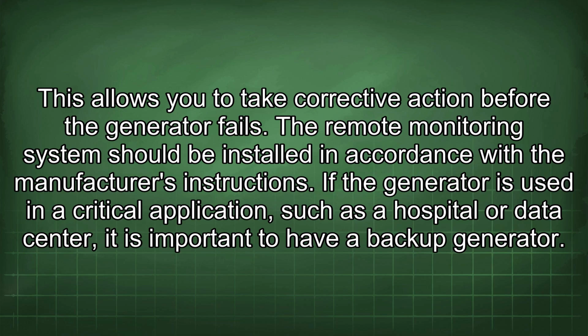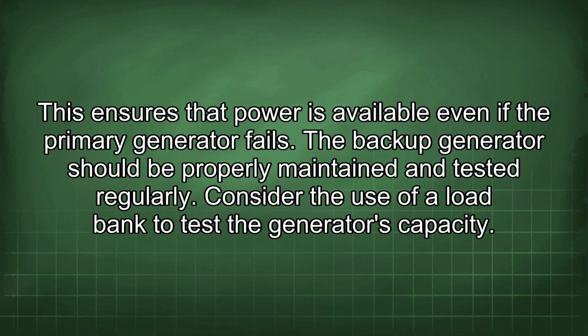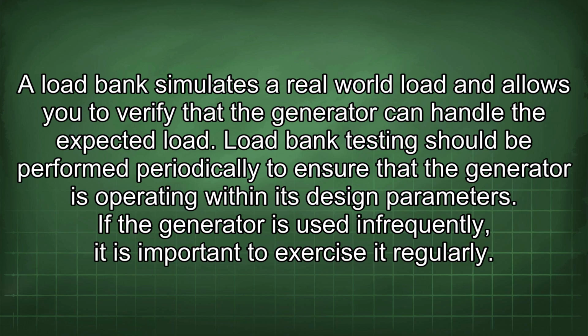If the generator is used in a critical application, such as a hospital or data center, it is important to have a backup generator. This ensures that power is available even if the primary generator fails. The backup generator should be properly maintained and tested regularly. Consider the use of a load bank to test the generator's capacity. A load bank simulates a real-world load and allows you to verify that the generator can handle the expected load. Load bank testing should be performed periodically to ensure that the generator is operating within its design parameters. If the generator is used infrequently, it is important to exercise it regularly.